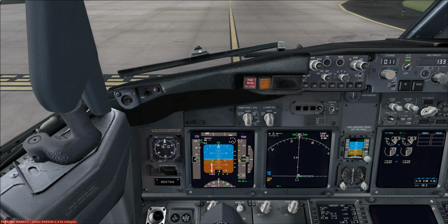In the event of terrain contact, a landing gear down might cushion the impact to even save the aircraft if the ground contact isn't too hard. And being in landing flaps and retracting the gear may cause a configuration warning, which can be distracting and increases stress in the cockpit. Also, retracting the flaps during a windshear escape maneuver would cause a loss in performance for the escape.